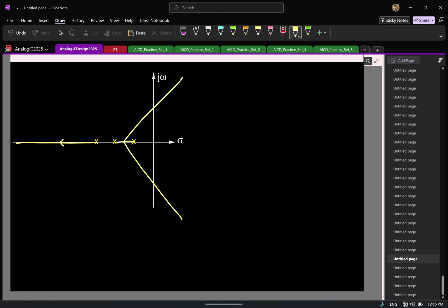So now, do you think a third order system can be unstable? Yeah. You see that for any DC gain greater than this point, I'll call it A0 prime. For A0, the DC gain, if you make it greater than A0 prime, this easily becomes unstable. Now note that if this DC gain A0 prime is really large, say 1 million or 10 million, then we are at least okay, right? Because at least till 1 million DC gain we are okay. But it turns out this value is very small. I'll give it in the practice problem. So that's why this is a problem.